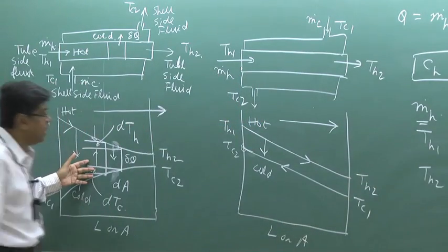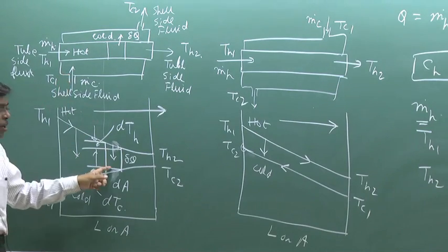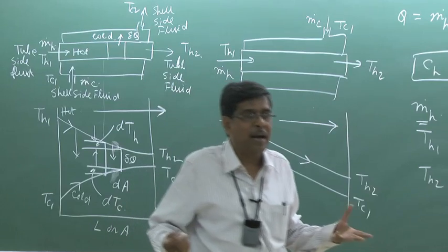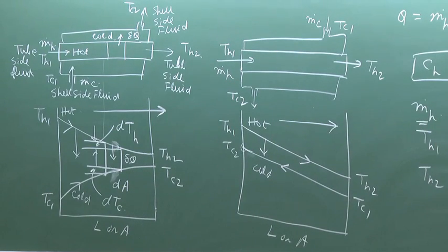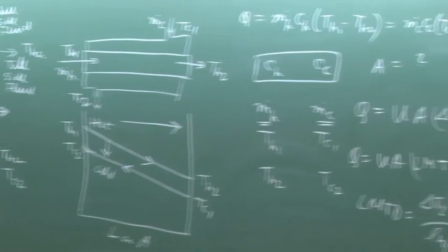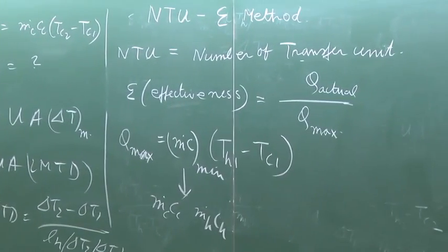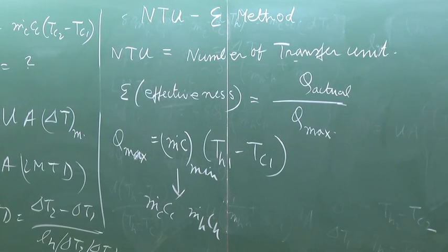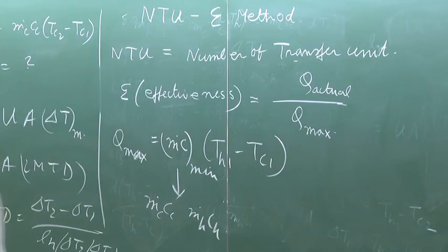But here, even if you give an infinitely long exchanger, it will never reach. Delta S universe can be 0 in an ideal situation of a reversible, quasi-static process, but can never become less than 0. It is impossible. So in a parallel flow heat exchanger, it is not feasible at all by the physics. So then what happened?